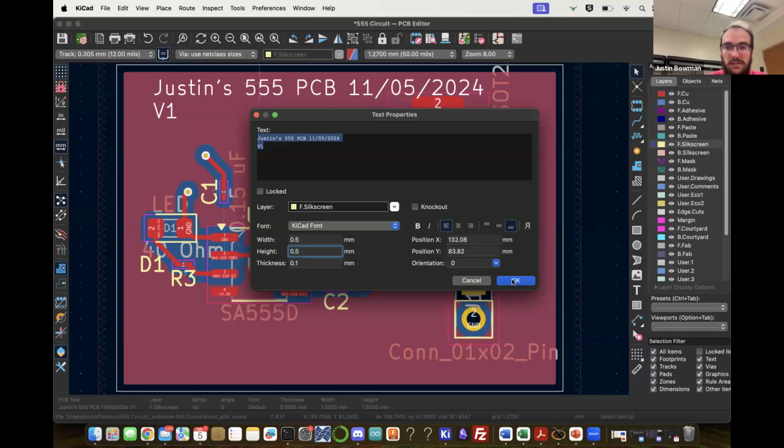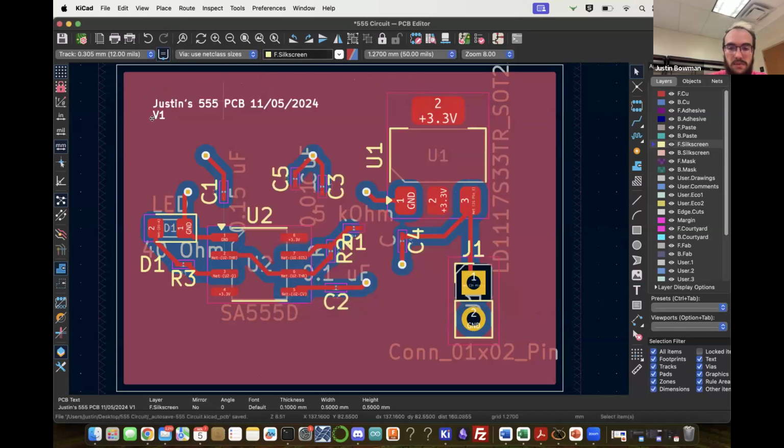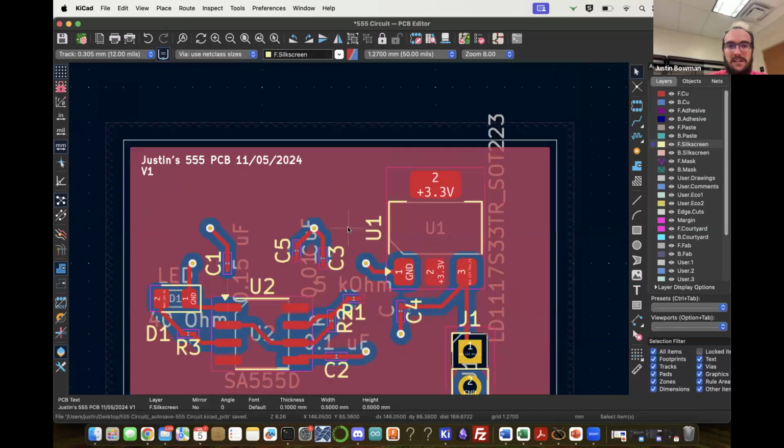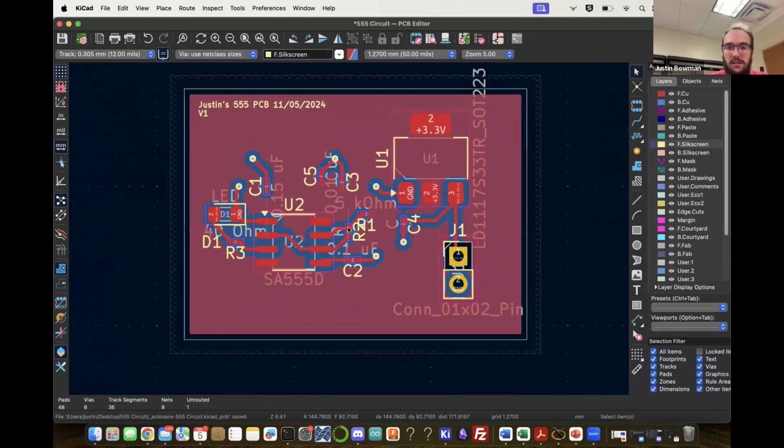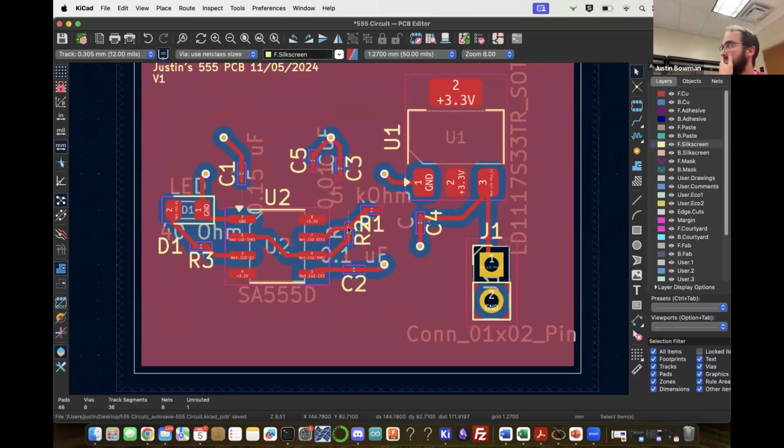I think we never talked about some of it, but it's good to do things like when you're routing high speed traces: don't make 90-degree bends. Don't route under other components. Especially if you're doing RF things, those matter. This is the bare minimum of things that you have to think about, but there are other tools like that on here.